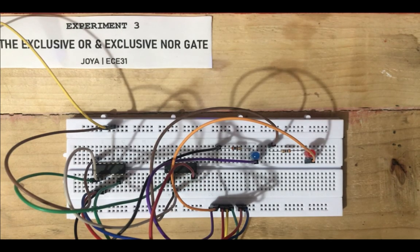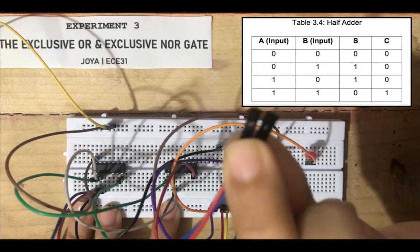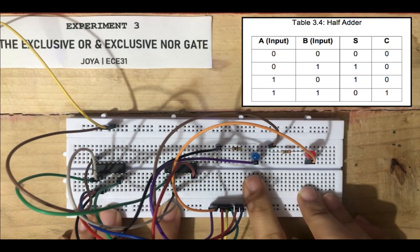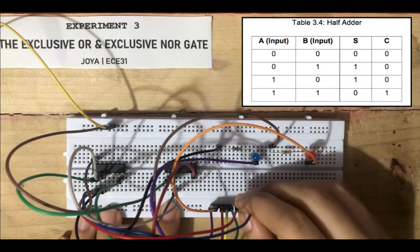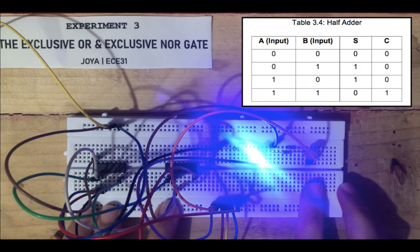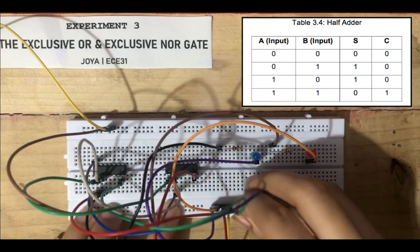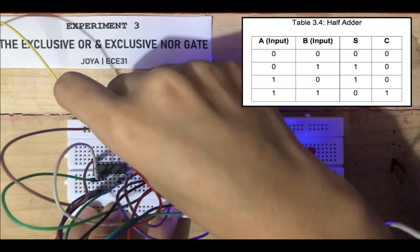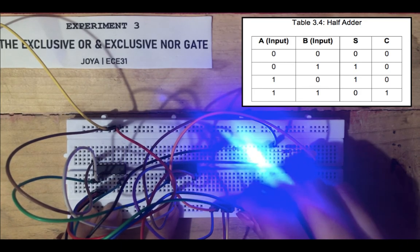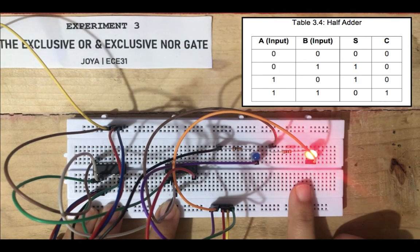The results of the half adder circuit show that when both inputs A and B are 0, the outputs S and C are 0. But when B is 1 and A is 0, S is 1 and C is 0. When A is 1 and B is 0, still S is 1 and C is 0. But when both inputs A and B are 1, S is 0 and C is 1.